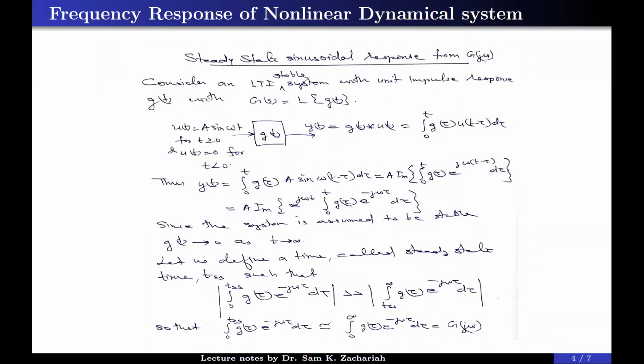So to be on the safe side, take 2 volt offset, so that if supply voltage is plus or minus 15 volt, you put an integrator limit of plus or minus 13 volt. I think this is your doubt. Yes, sir. Okay, that's all. Anything else for anybody?